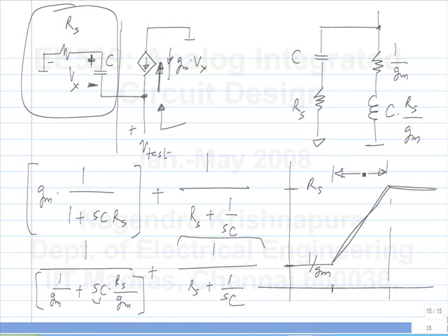We don't have an actual inductor, but we do get inductive impedance. This again is familiar to you using gyrators and other concepts that you have learnt in other courses. You can get inductive behavior by using only capacitors and control sources. The idea is that an inductor integrates the voltage to give you a current, whereas a capacitor integrates the current to give you a voltage. By using control sources, you can swap the current and voltage, so instead of getting an integral of the current, you get an integral of the voltage. That's what a gyrator is, right? This is some very simple realization, a single transistor realization.